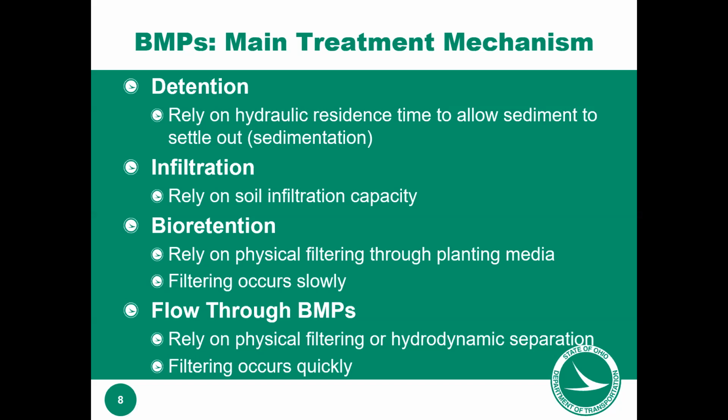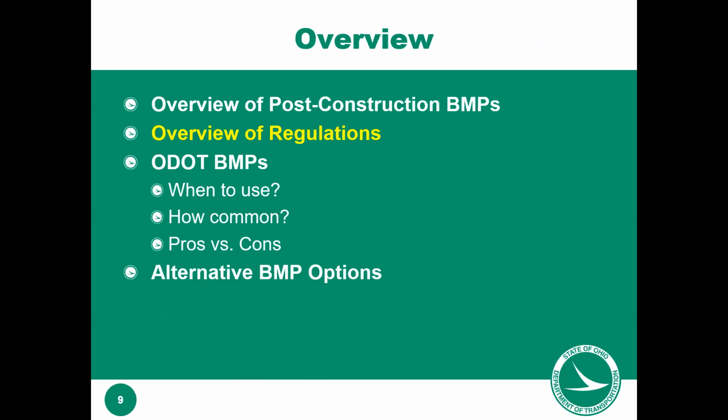So any of those high flow-through things that are called bioretention cells by the vendors, and other states call them bioretention cells, but anything where water goes through quickly and is held back in a big area in Ohio is not bioretention for ODOT and Ohio EPA. The locals can call your BMPs whatever you want, but that's kind of how those work. So that's the big picture overview of post-construction BMPs. Let's get into the regs real quick.